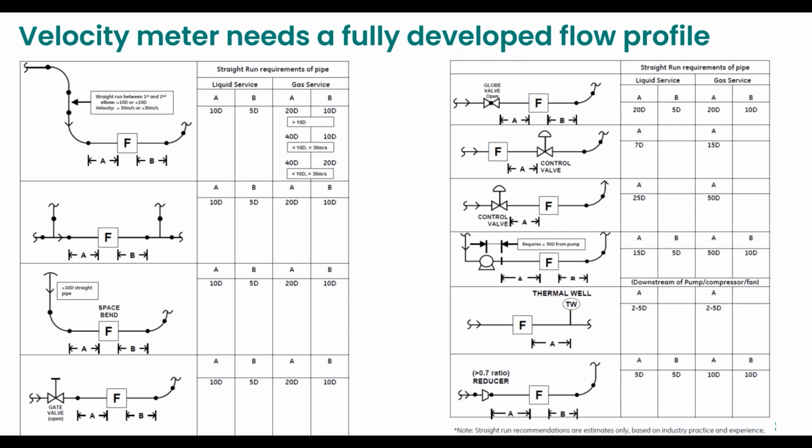If we have a single path and we measure at the center of the pipe, it obviously tends to overestimate the velocity there. So we have correction factors that run automatically in the electronics, to apply a 0 point something depending on the flow profile that is expected from a Reynolds number point of view. But we need this flow profile to be developed.